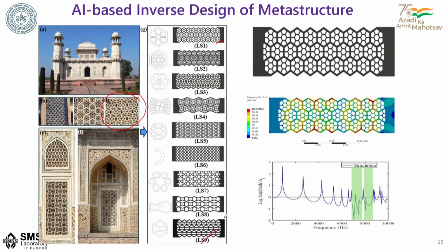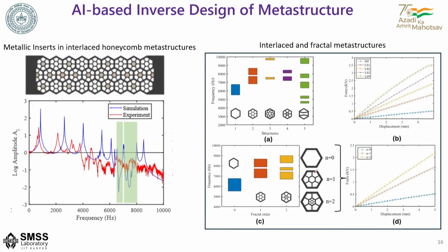You can see that we have been able to discover 9 different patterns, and for each one of them, with the help of certain modifications, you can create attenuation band gaps. So, keep a curious eye out for this kind of periodic systems. Here you see, with the help of certain additional mass we can create this attenuation band.